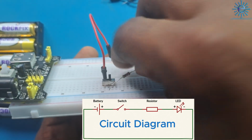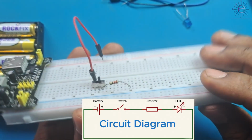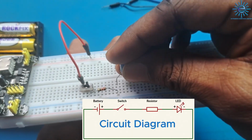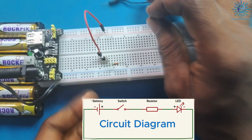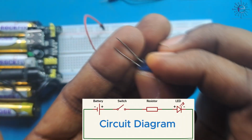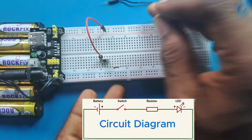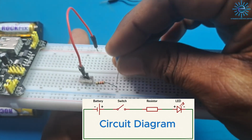And then I'll connect the other leg of the resistor somewhere here. And I will connect the positive leg of my LED to the other leg of the resistor. Remember that the positive leg of the LED is the long leg. So if I put the two legs together and check, the long leg is this one. So I will connect it to the other leg of the resistor, which is not connected to the middle leg of the switch. So I will connect it like this.